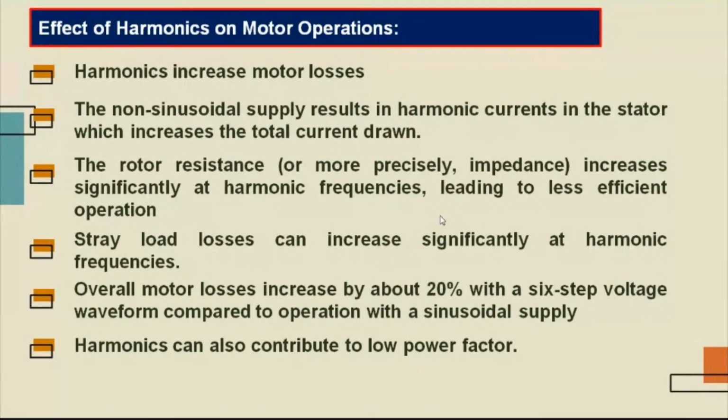Next point is stray load losses can increase significantly at harmonic frequencies. And overall motor losses increase by about 20% with a 6-step voltage waveform compared to a sinusoidal one. So this whole checklist we have to note down, because improving all these things will ultimately result in better efficiency of the system and better productivity of that particular site.